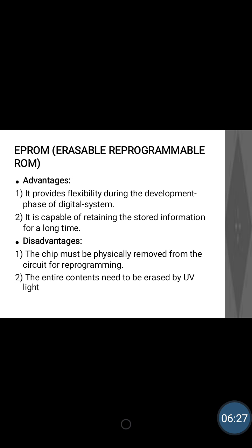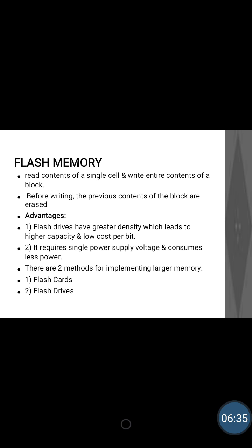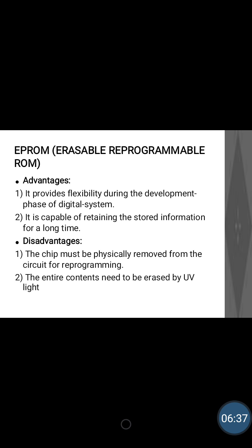It provides flexibility during the development phase. It is capable of retaining the stored information for a longer time. The disadvantage is the chip must be physically removed from the circuit for reprogramming. This is much more complex, isn't it? The chip has to be removed and then inserted back. The entire content needs to be erased by UV light. Then it can be reprogrammed.